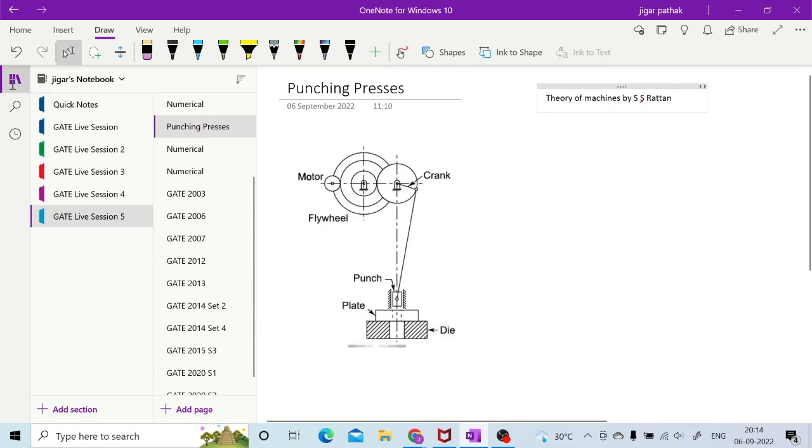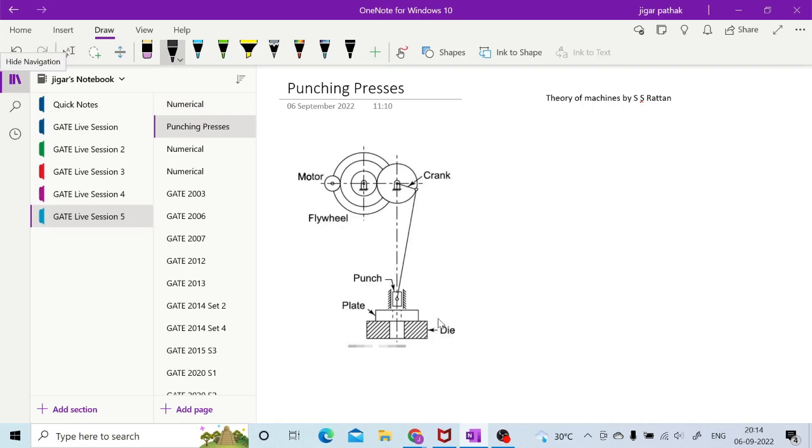After that, you have the application of this flywheel in a punching machine, or punching press, as you can see here. Here this stroke is used to punch the plate. Whenever this particular distance is traveled, most of the power is required. Excess power is required when you are going to cut the material in your punching press. Otherwise that much power is not required. So here also you have the requirement of a flywheel. Similarly in riveting operation also you require this, right?